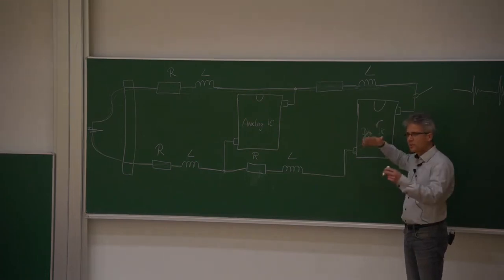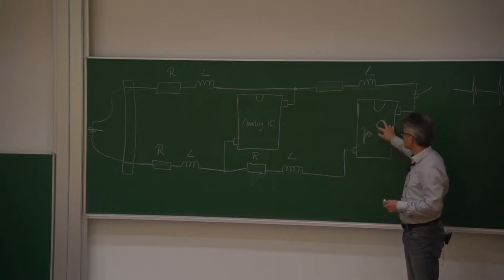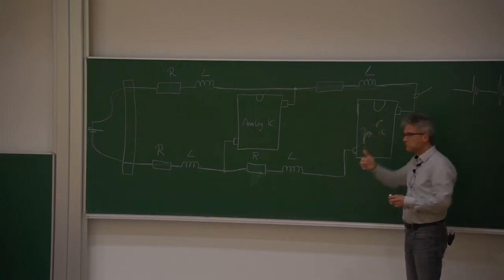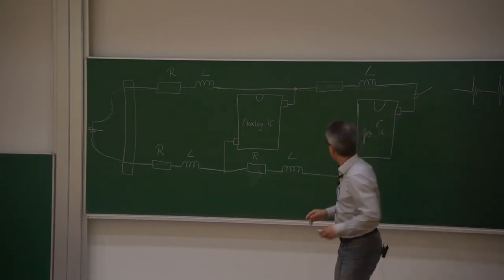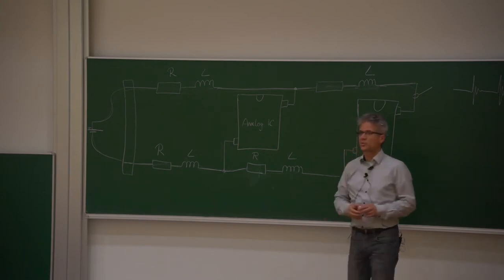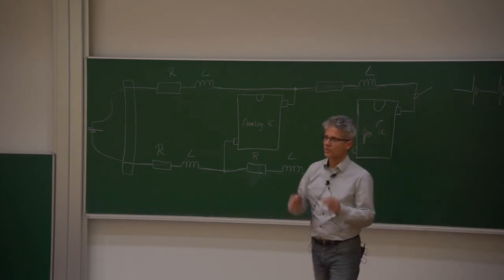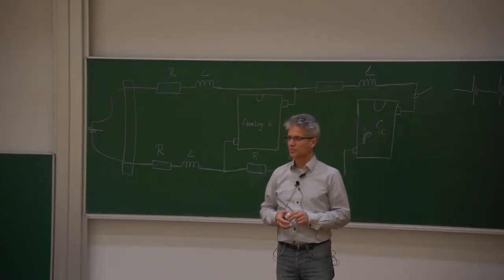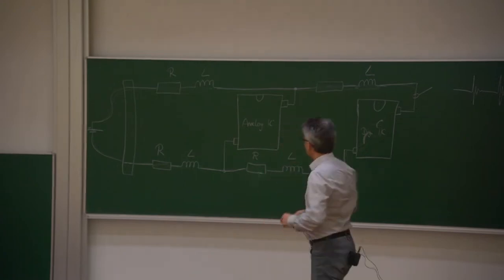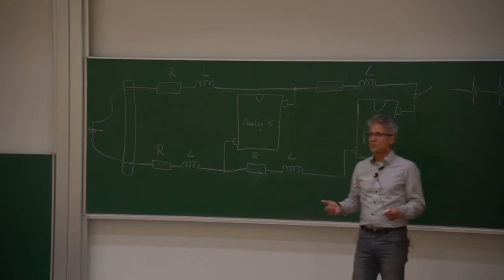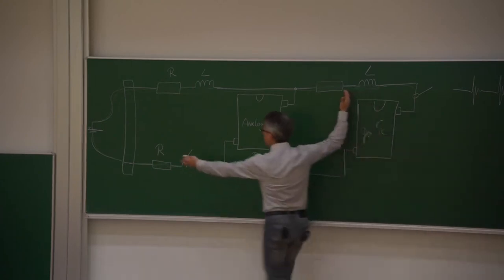And then out of several statistics and measurements, they came to the conclusion that in roughly all cases, 1 millimeter of bond wire or 1 centimeter of this printed circuit board trace has 7 nanohenries or 3 nanohenries or whatever is written in the textbooks. And this gives you some kind of rule of thumb. But in reality, it's completely stupid, because it really depends on how big this loop is.